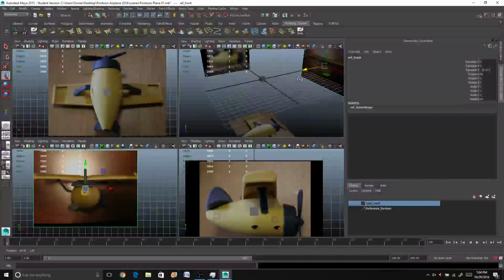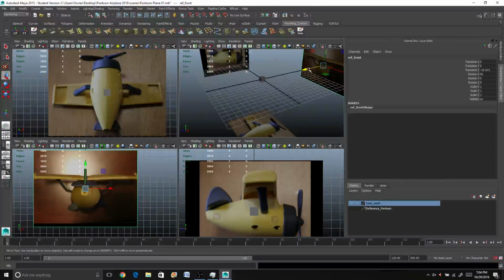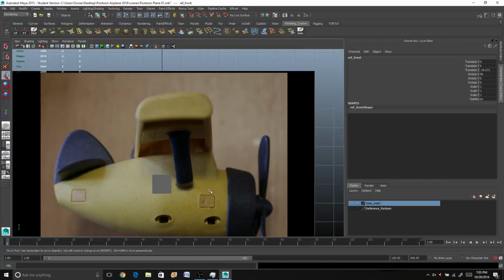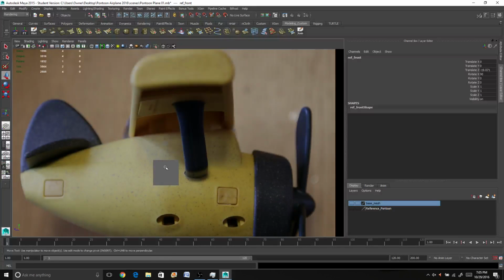All right, so now my grid space over here is all opened up, and now I can model, and I can keep the box in view on all sides here, and I'm ready to go. So I already have my cube, so I'm going to start from my side view here, press spacebar, and I'm going to go to vertex mode.